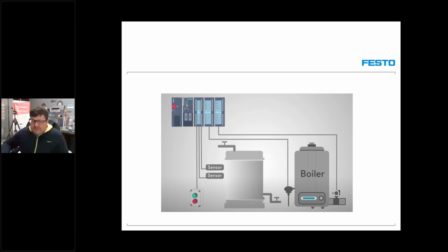Okay, guys, this is a summary of all the different types of sensors that can be wired into your PLC. That means I need to wire my push button and my emergency stop, for example, or my level sensors for high level and low level, proximities, or a thermocouple or a transmitter that actually sends the temperature inside the boiler, or maybe the water level in that boiler. All this can be wired into my PLC. That means analog signals and digital signals can be wired into my PLC.